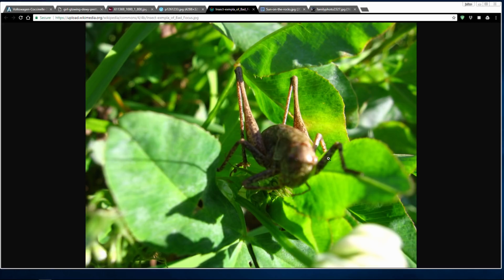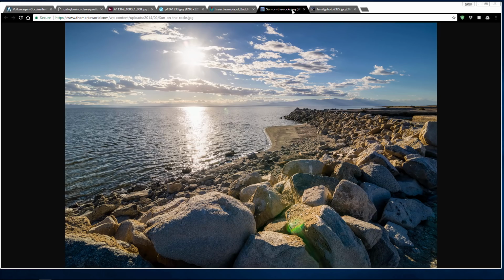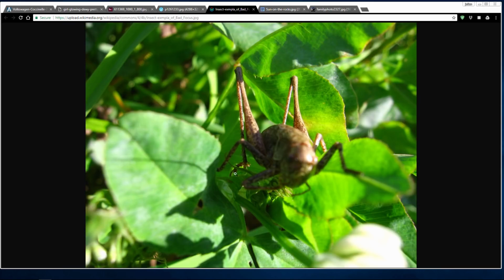Sunny. If it's sunny, like in this picture or this picture, for example, if you take images on a sunny day, it will be complicated too, because afterwards you will have to put light again in the 3D software you use to make the shading and the shaders. If there is already light information in the color map, it will not work, especially with direct light. So with sunlight, every direct light, it will not work.